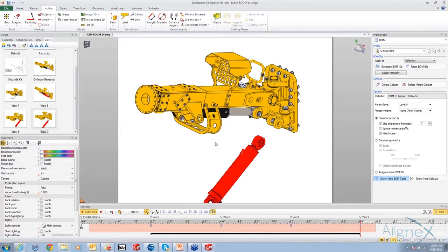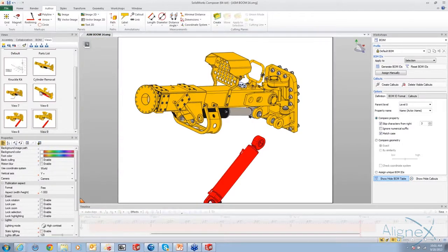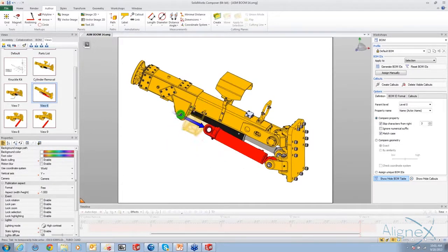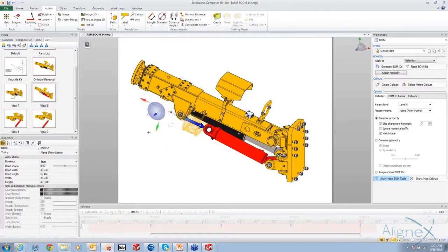Can you create a style for an arrow, color, and scale? Absolutely. Anything that you can change, you can create a style for. So every property has the ability to change the style. And you can control, and what we call subscribe and unsubscribe, components to specific styles. So if I'm looking at a specific arrow, when I select on that arrow, I can have full control over what I want to happen to that.